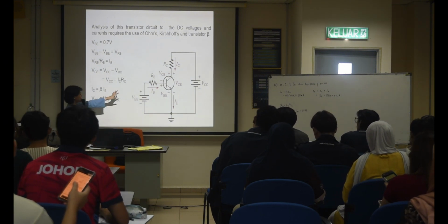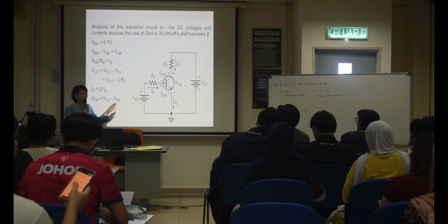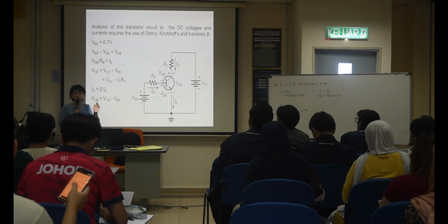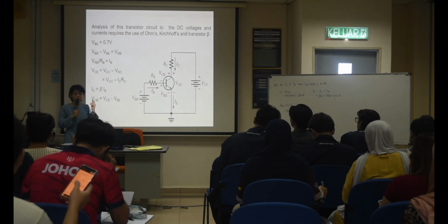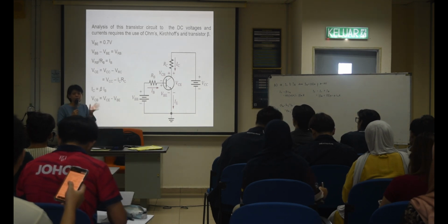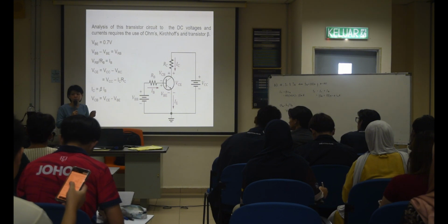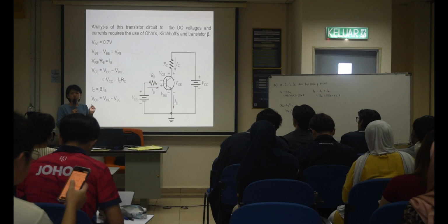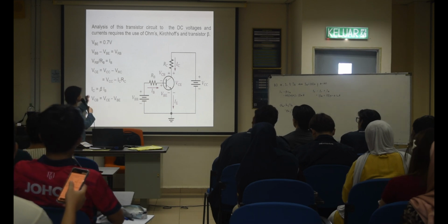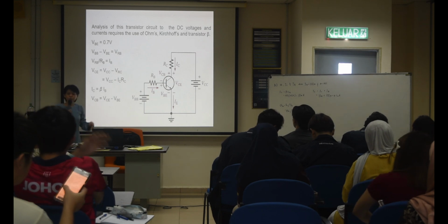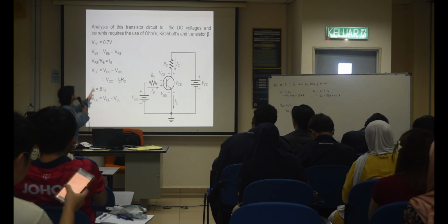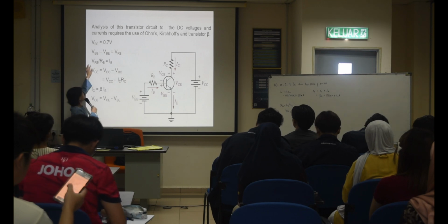Okay. Theoretical calculation uses 0.7. Some questions will ask you to use 0.65. That one is germanium, or 0.4. These two types, they will ask you to use 0.4 or 0.65, depending on the question. If they say using germanium, it's 0.4. Silicon normally is 0.7 or 0.65. But if the question is not given, assume 0.7. That's the easiest. But normally I will give that.